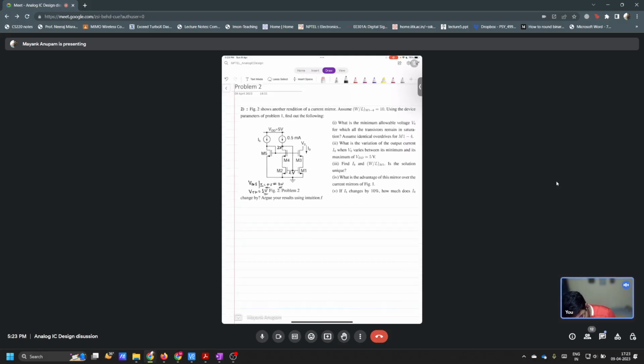So tell me, where should I bias? This voltage is now not controlled by these two voltages, 2 volts and 2 volts. So who sets these two voltages? Or even before that, who sets this voltage here? What sets the voltage at the drain of M2? VDD.